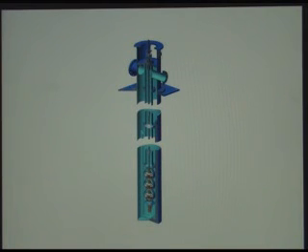And what this does is it sets at grade, the motor's above grade, but you have to dig a great big hole in the ground for the pump to sit in. And it's a can because there's an outer containment shell that contains the fluid. So the pumpage comes in, goes down the containment shell to the pump suction. The pump at the bottom of this shell pumps it up and then out. And this is what we use when we have boiling fluids that are basically right at the pump suction.